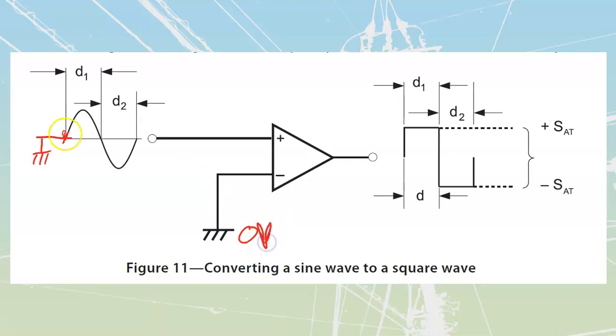That 0 volts we have over here, the second we go a little bit positive, and we see we are coming into the non-inverting, therefore it is going to switch almost instantly. Because we've got that 200,000 gain, it is going to drive hard and fast into the positive. So there's going to be a tiny, tiny little lag over there. That's going to be just a small horizontal line, then it drives all the way up, and then it is going to stay high until it gets down below here, and then all of a sudden it's going to drop down, then there'll be a tiny, tiny little line, and then it'll go down into the negative.